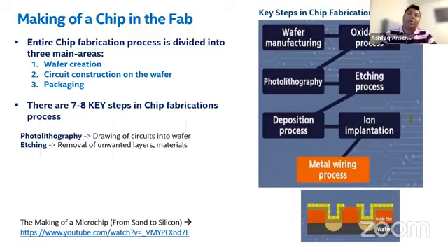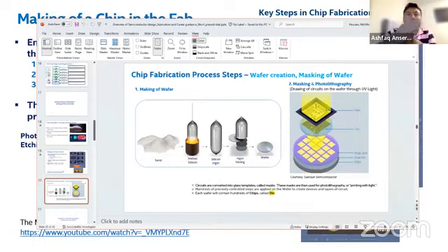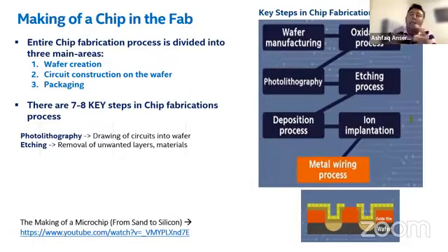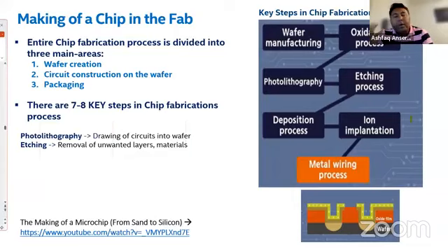Now that you have a wafer, we have to prepare it. Like pizza, you have to clean it and prepare the surface. So you see the ingot, we cut it, and then we clean it, polish it, and oxidize it with a silicon dioxide layer. Why do you oxidize? Think about iron. If you leave iron outside, it will rust and get corroded.